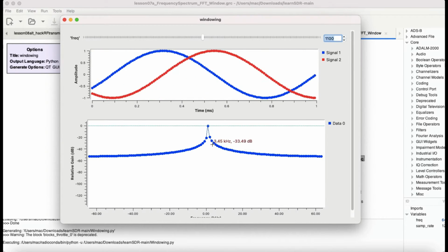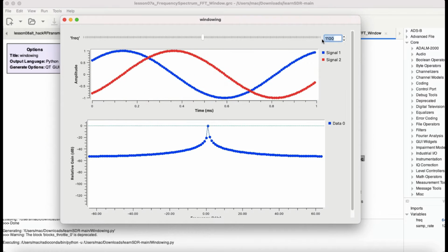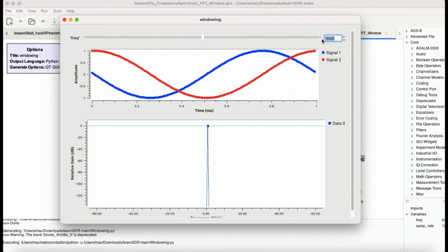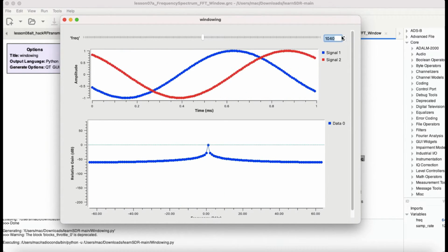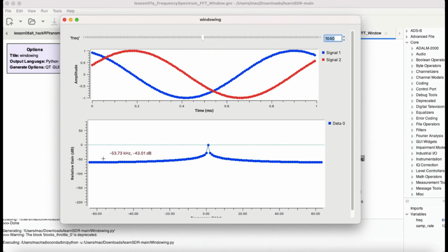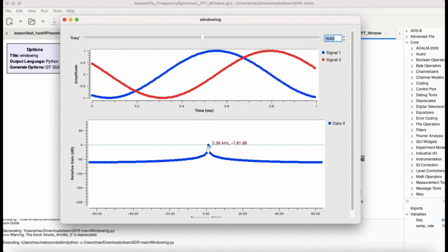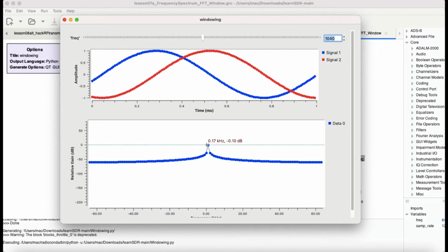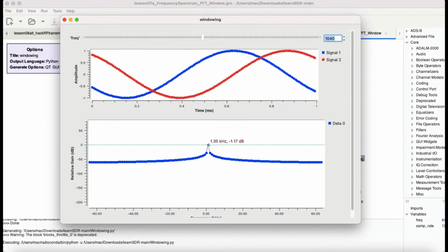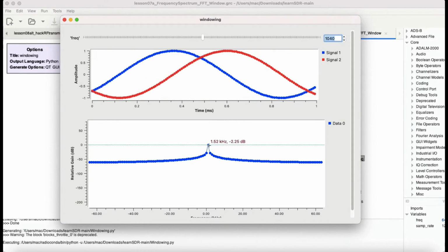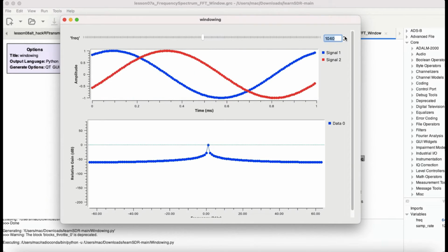These side lobes, if you were to look at it at 1 kilohertz, you can do it for any multiple, they are just way down here. Let me just show you. The noise floor is somewhere around -150 dB. Now when I change this to 120, all of a sudden my noise floor jumped to -50 dB. And you would start observing these points. This point, which is the peak of your signal, will start taking over the next bin, as it's not going to be an integer multiple.